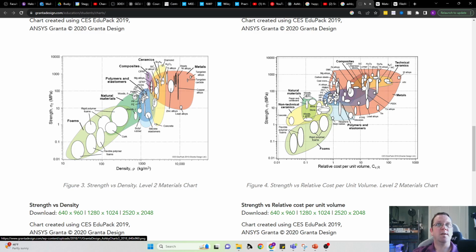So alumina, very, very commonly used. So alumina actually as a ceramic is pretty tough stuff. Not to be confused with aluminum. These are aluminum alloys. So alumina is a ceramic, aluminum is the metal. Very big difference there. So the aluminum alloys are fairly lightweight. They can actually get to be pretty strong in some of the same ranges as some steels. Zinc alloys are a little heavier, but they're also corrosion resistant and all of those things. So there's a lot of range.